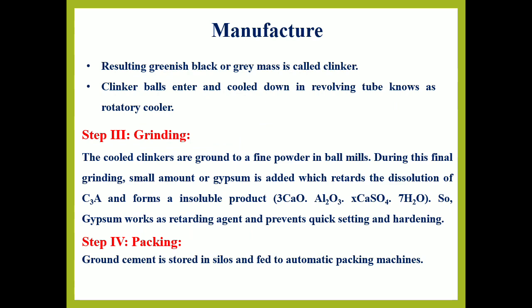From the reactions, a green, black or greyish mass is produced, which is known as clinker. This is formed in balls, and these clinker balls enter rotary coolers where they get cooled down. After this burning process, we go for the grinding process.